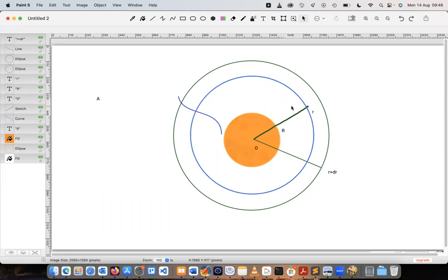So even if it's Z, we always wrote in terms of Z and Z plus delta Z. So here we'll always write what's coming in is at r and what's going out is at r plus delta r. And then the fact that the flux is in the opposite direction will just change the sign of NA. So if it looks confusing, we know A is fluxing in. Why are we writing as if it's fluxing out? It's because that's the general way to write these balances, and the sign of NA will take care of the actual direction for the balance.